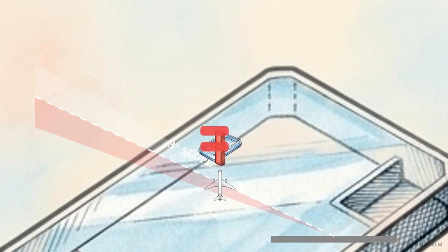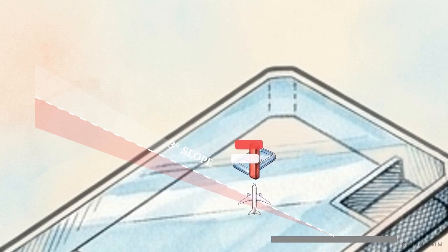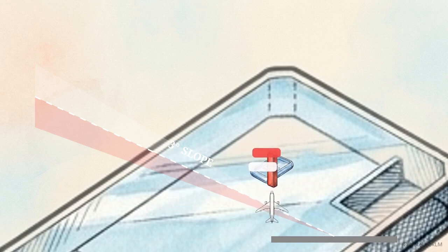Fly above the proper slope and you see 2 white bars. Drop below it and both bars shift to red. To guarantee clearance from ground obstructions, the pilot must maintain the exact boundary between the 2 beams. When perfectly on slope, the near bars appear white and the far bars appear red.